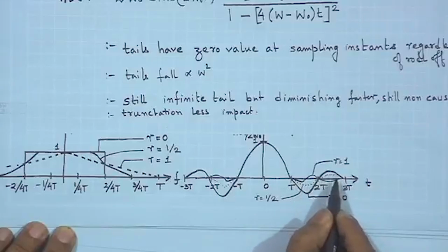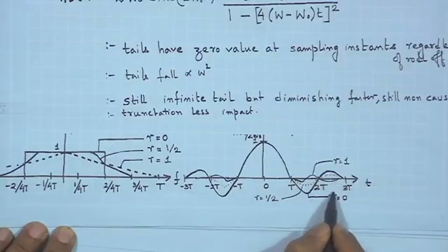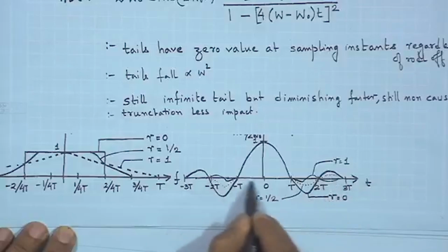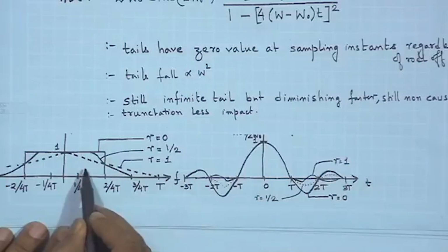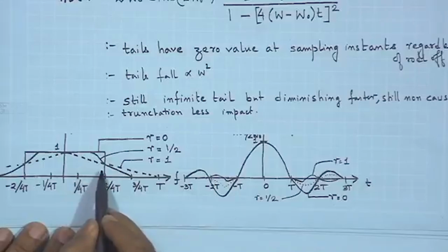So, by choosing an appropriate value of R, one can design a suitable pulse, and there would be a corresponding implication on the spectrum that is occupied. Now, what you get is a much more realizable situation. However, what you pay is excess bandwidth, which is not required for communication, but you need it for practical realization.